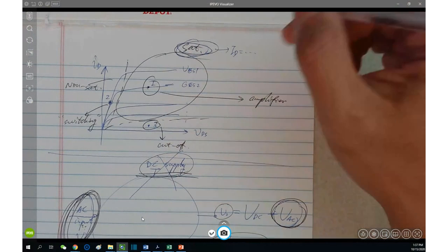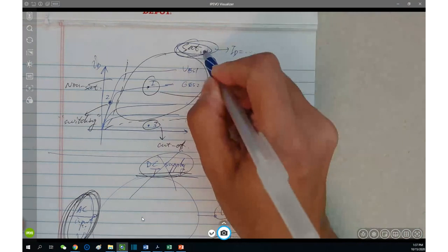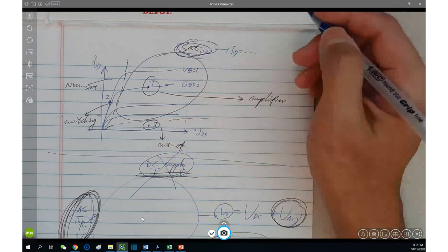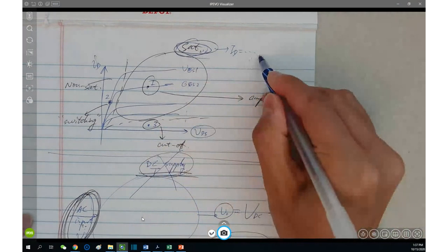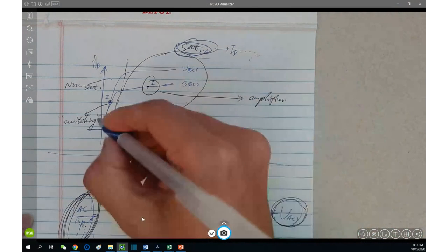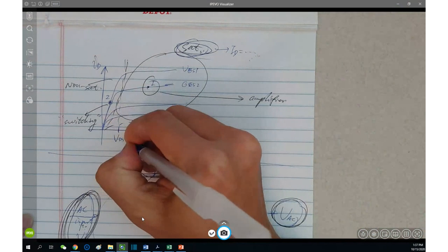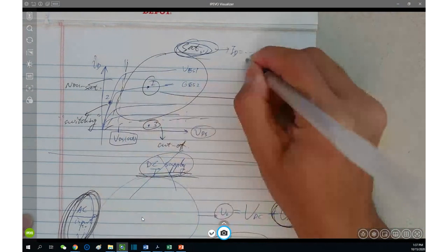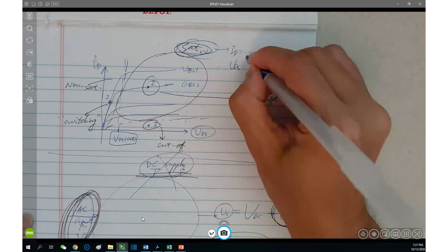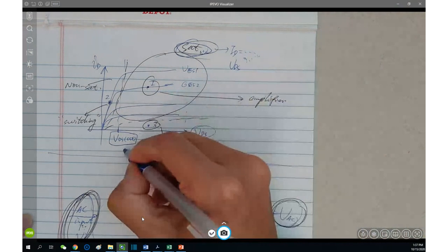And then you calculate ID, VGS, VDS. And then you need to verify the saturation assumption, right or wrong. How to verify that? Because you calculate the VDS from here, your VDS has a VDS saturation boundary voltage. If your resulting VDS, based on this assumption, is greater than that...